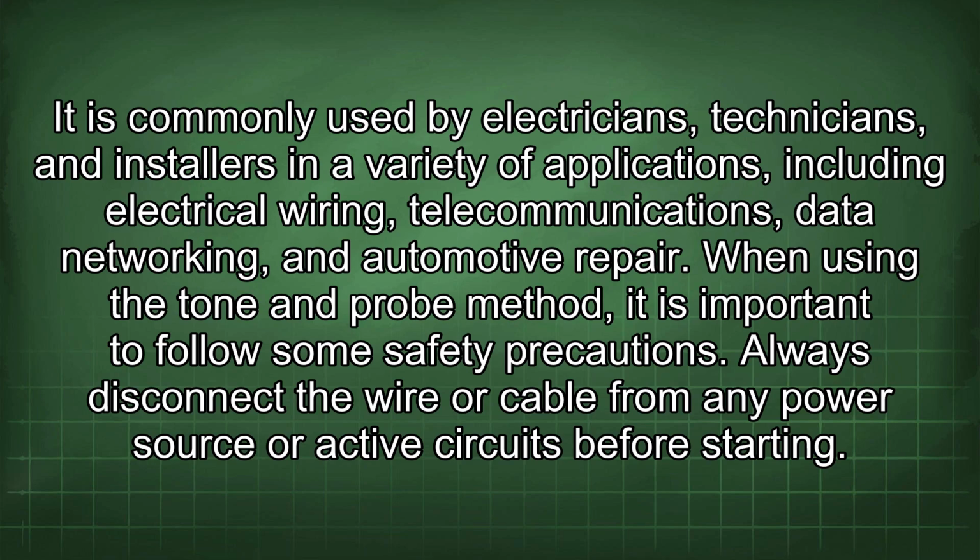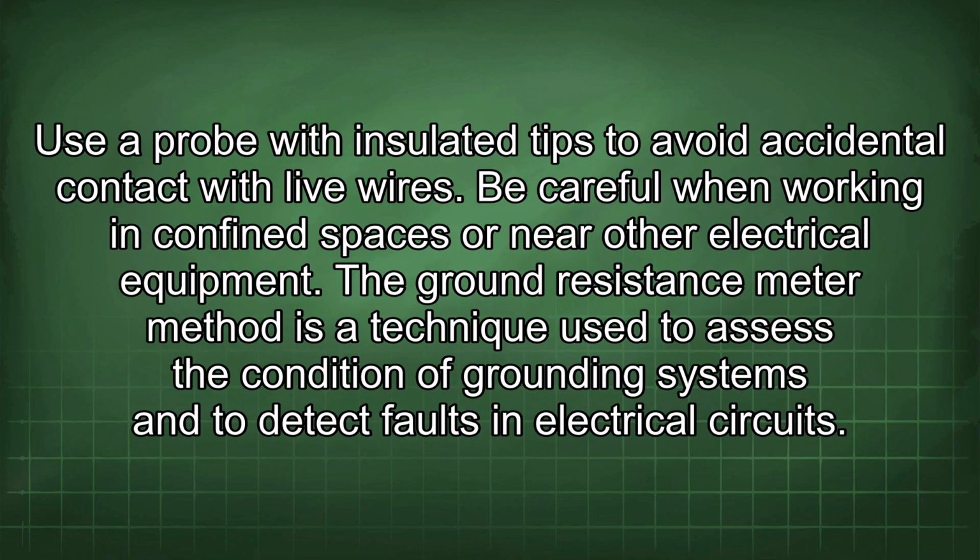When using the tone and probe method, it is important to follow some safety precautions. Always disconnect the wire or cable from any power source or active circuits before starting. Use a probe with insulated tips to avoid accidental contact with live wires. Be careful when working in confined spaces or near other electrical equipment.